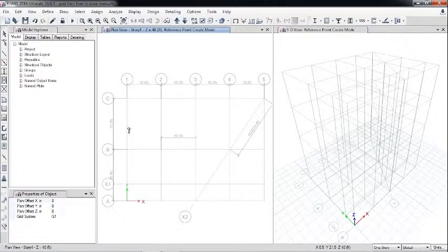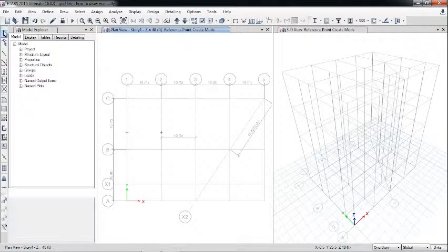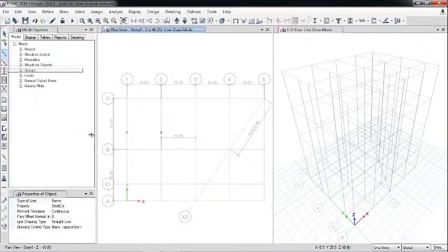For example, I want to draw a beam from this point to this point, from center to center, or maybe at 5 feet above from the B axis. So here I will put in the y direction offset 60 inch, meaning 5 feet. Here I have drawn 1 point, here I have drawn the second point. So now these are just reference points for my drawing purpose. Now when I draw a beam member, it will automatically pick these points. Okay, then the drawing will be accurate.